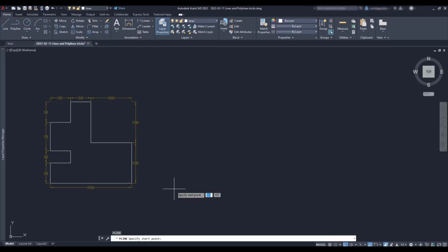Then I'm going to draw this irregular polygon, and let's make it beautifully starting at the same horizontal plane. First, make sure Object Snap and Ortho Mode are on. The snaps are off. Let's turn them on. I'm going to hover this endpoint, drag to the right following this track line, and then I type 200 mm to start a polyline at that distance from the corner.